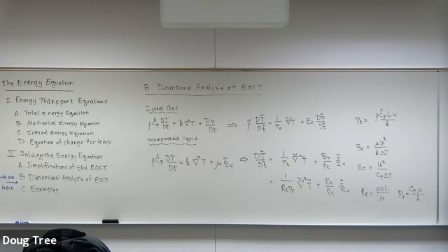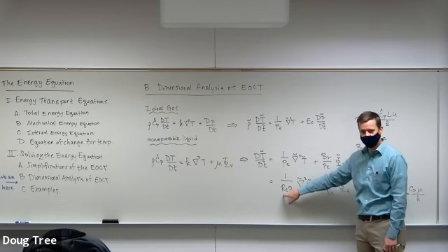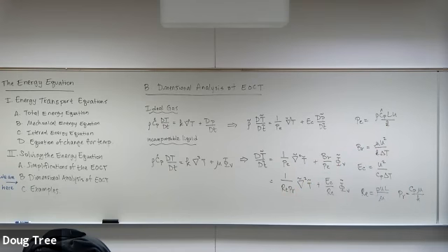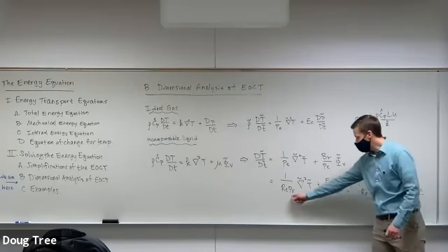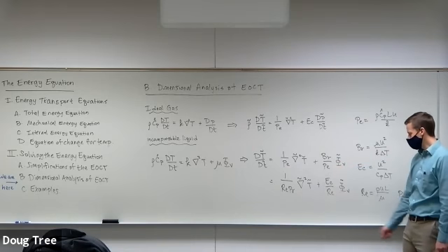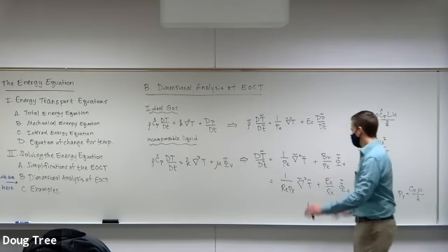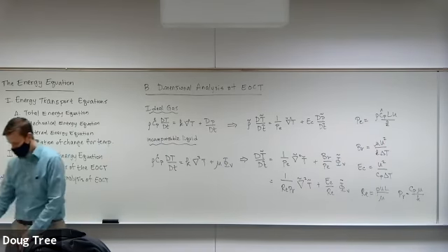And then one thing we didn't say, but you can rewrite a lot of these dimensionless numbers in terms of each other. You can rewrite a Peclet number as the product of the Reynolds and the Prandtl number. These are both numbers that we've encountered before, back when we were first talking about diffusivities and ratios of diffusivities. The Prandtl number is the ratio of the momentum diffusivity to the thermal diffusivity, and the Reynolds number we know very well, so that gives you a Peclet number. Instead of writing this as the Brinkman number divided by the Peclet number, you can write this as the Eckert number divided by the Reynolds number. So that's kind of interesting too. You can maybe see a relationship between the dimensionless numbers there, but I don't know too much to take away from that.